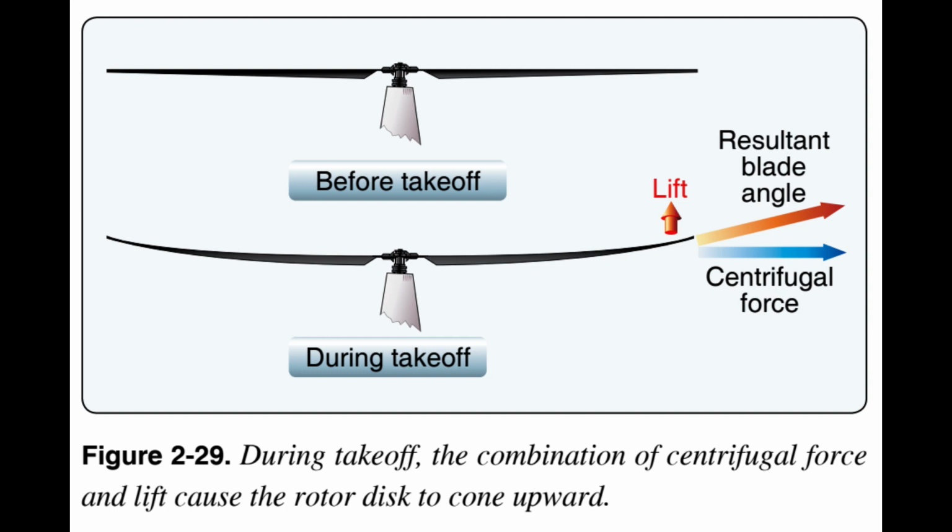Because the angular momentum must, by law of nature, remain the same, no external force applied, the angular velocity must increase. The rotor blade rotating about the rotor hub possesses angular momentum. As the rotor begins to cone due to G-loading maneuvers, the diameter of the rotor disc shrinks. Due to conservation of angular momentum, the blades increase speed even though the blade tips have a shorter distance to travel due to reduced disc diameter.